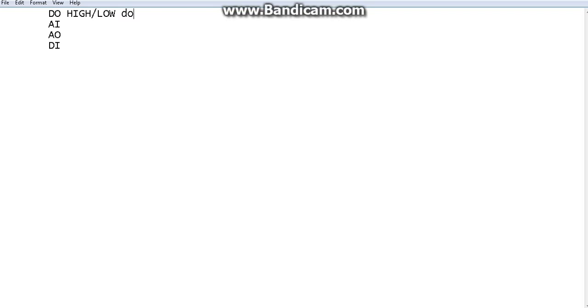So the keyword is digital write. When it comes to analog input, we are taking values from 0 to 1023, or in other words 0 to 5 voltage values, and the keyword here is analog read.